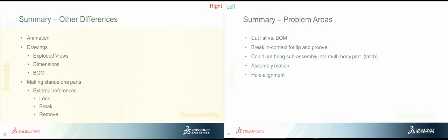And one other thing, the hole alignment tool for checking the alignment between two hole features, when you talk about a base part and a derived part like we did, in other words, in my assembly that I ended up with, if I wanted to use the hole alignment tool, it wouldn't have worked at all. It only works in the parent stuff. It would look like you don't have any hole alignment problems, but it just wouldn't find them. It's in the help file. It says this is a limitation of the hole alignment tool. It won't work on multi-bodies where you save the bodies. So be careful of that.